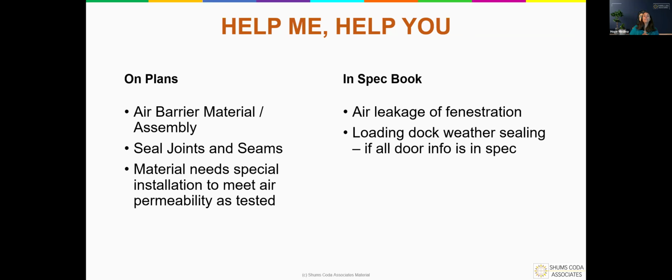A lot of times I see "air/moisture barrier," which in my opinion does not specify it enough. You've got to make sure that the contractor out in the field knows exactly what they have to pay attention to as far as joints and seams, right? Which leads us to the next one. How are we sealing up all those joints and seams? How are we sealing up the penetrations? All of that is incredibly important.